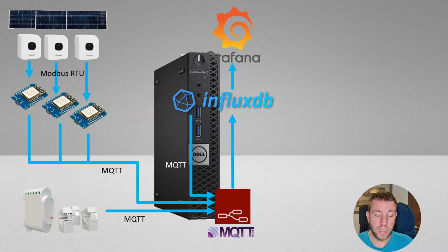And so the first thing that I did, because I knew that I wanted to display this information on the touch panel as well, I sent this information from InfluxDB back to Node-RED using MQTT. I could have done it the other way, but that was an interesting new feature, how you can create a task in InfluxDB to send data over MQTT. And it could be useful for other scenarios as well. So that is yet another piece of information which comes back from InfluxDB.